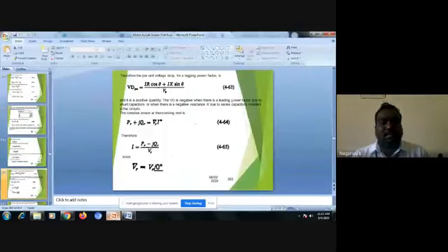So the complex power at the receiving end is PR plus jQR. I have taken PR plus jQR is equal to VR bar into I conjugate. I get, okay, these things you know that I is equal to PR minus jQR divided by VR.